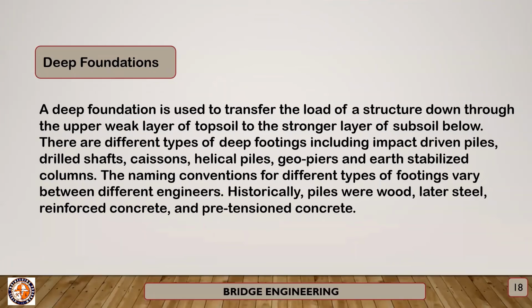Deep foundation. Next is the deep foundation. A deep foundation is used to transfer the load of a structure down through the upper weak layer of topsoil to the stronger layer of subsoil below. There are different types of deep foundation, including impact-driven piles, drilled shafts, caissons, helical piles, geopiers, and earth-stabilized columns.